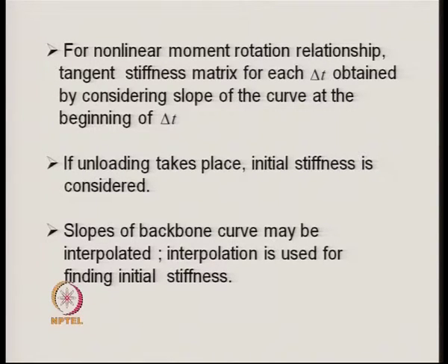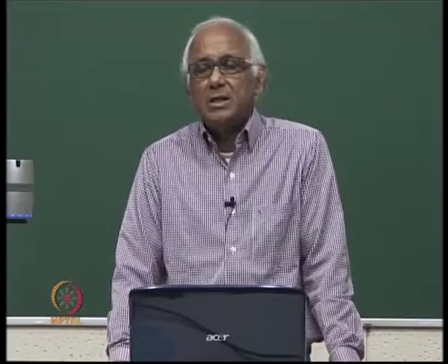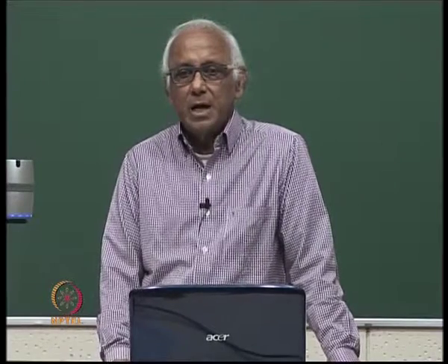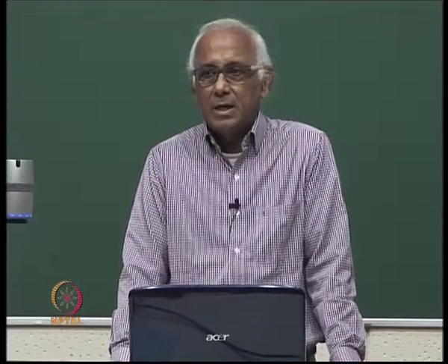Now, if the moment rotation relationship or the force displacement relationship is not idealized as a perfectly elastoplastic or bilinear curve, but by a nonlinear curve, then the tangent stiffness matrix for each delta t is obtained at the beginning of the time interval delta t.